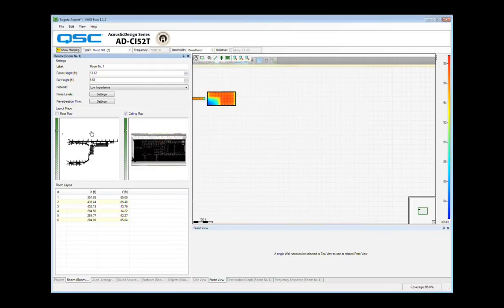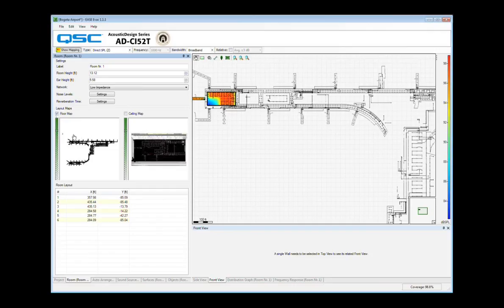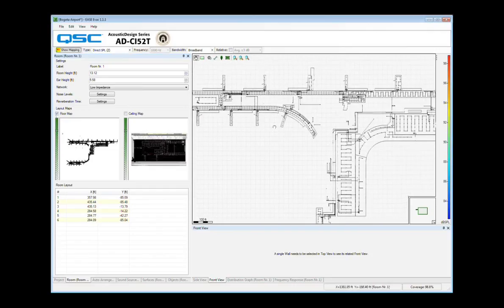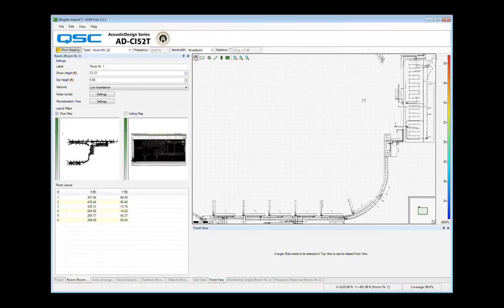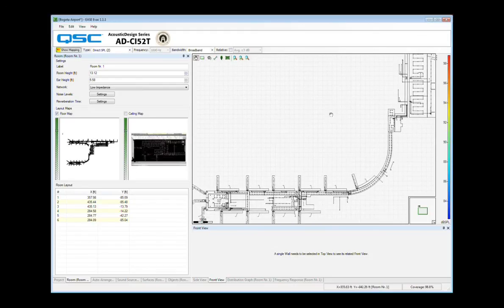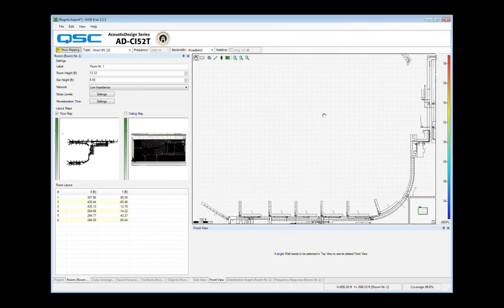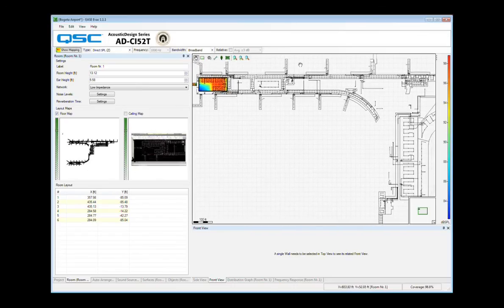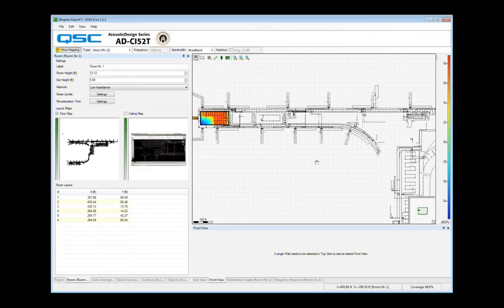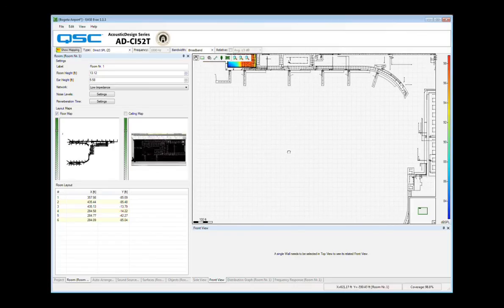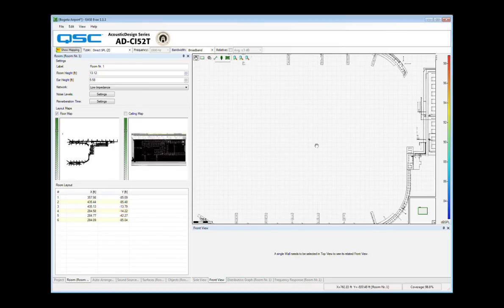One of the things that you want to do for a project of this size, though, is to probably divide it up into quadrants and do this quadrant, do this quadrant, do this quadrant. That's when the RTF report capability becomes really important, because then you can keep the project very responsive by not having hundreds and thousands of loudspeakers in it with 50 or 100 rooms, which does slow you down, but you can then combine all of them later.